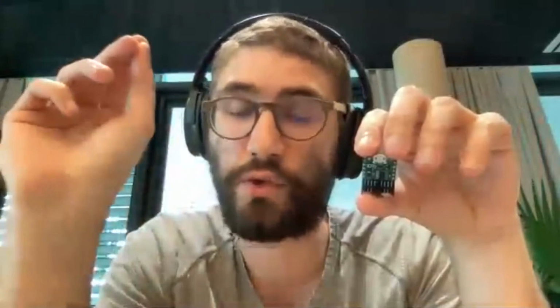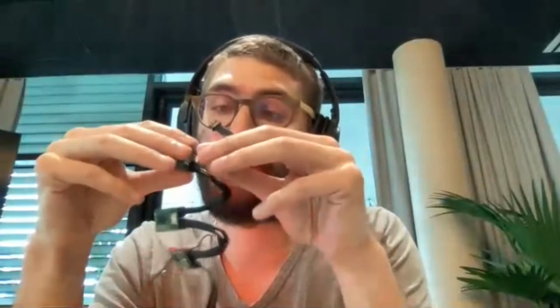This specific service just translates everything happening on the Luos side into a JSON format, and you can stream this JSON any way you want. In this specific case, I'm going to use USB, but you can use Wi-Fi or Bluetooth or anything you want. To make it work, I'm going to add this new board into my system, and I'm going to unplug my power because I'm going to switch to USB power. It will be easier for me.